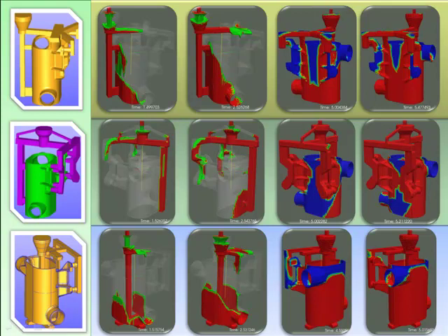This is an example of Cast-Designer CPI for filling simulation. There are 3 design solutions for an investment casting part. The first one and second one are side filling systems but with different designs, and the last one is a bottom filling system. The red color shows the hot liquid metal, and blue color is the air, which has not yet been filled. All the metal flow, air entrapment, velocity vector and pressure can be provided by Cast-Designer after the simulation.